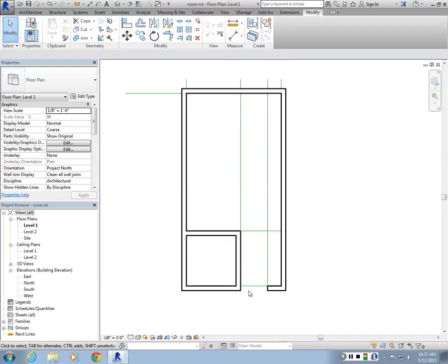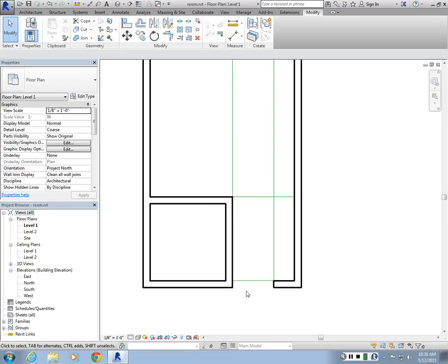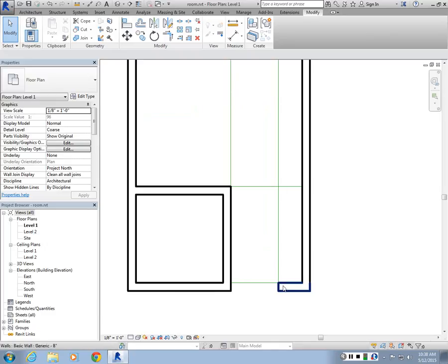Now technically, in order to place a door here, you want to have a wall. Doors are wall specific objects, so you cannot just place a door on its own. It has to be specified on a wall. Same thing goes for the windows as well. So this means my wall construction has to be first watertight, then we can place openings inside of it, right?